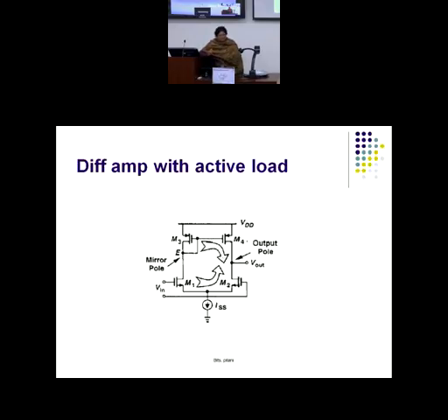But why is this not computed? You should know the reason. But yes, if this differential pair connects to the previous differential pair, then you need to take omega in into account. But remember, if a previous stage is there, then the input pole of the second stage automatically becomes the output pole of the first stage by default.